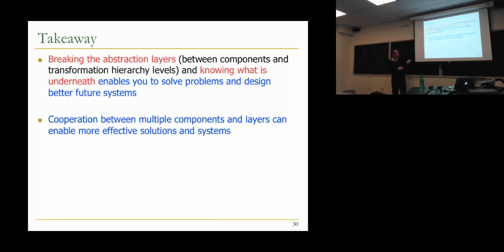Again, in this case, you can cooperate between the DRAM and the memory controller, or you can cooperate between the DRAM and the operating system. Even though in this case we evaluated the memory controller, you could say those rows are exposed to the operating system, and the operating system doesn't allocate any rows that cannot retain data for at least 256 milliseconds.